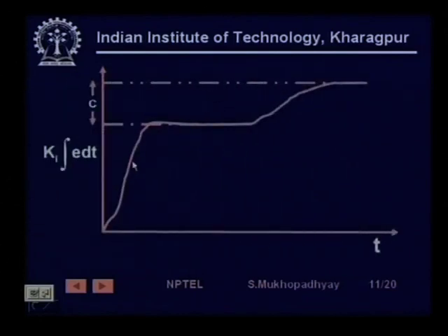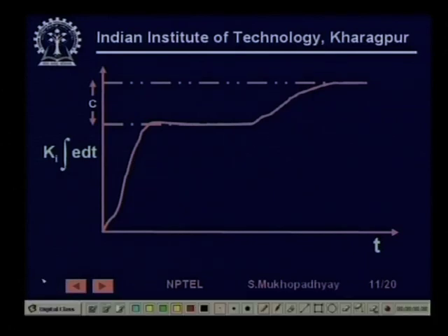So exactly this is what happens. Now you see, if you put the integrator, what happens is very interesting. This bias input which was previously given now comes automatically. The integral output which I was talking about increases till it can, then the error goes to 0. And if you change the set point again from here to here, again some error will be created and it will again integrate and will generate just enough output such that it can be sustained without the error.